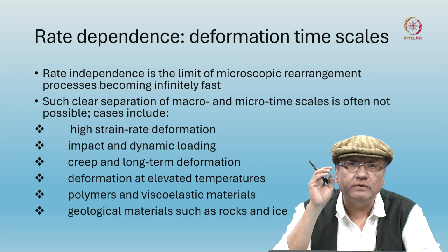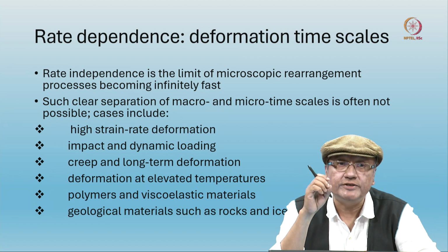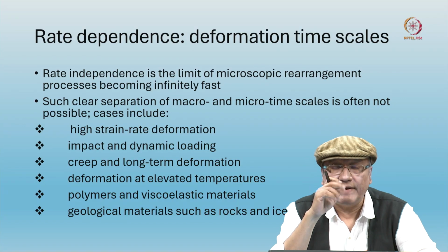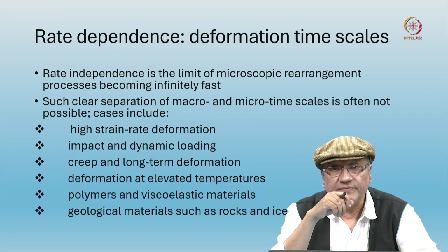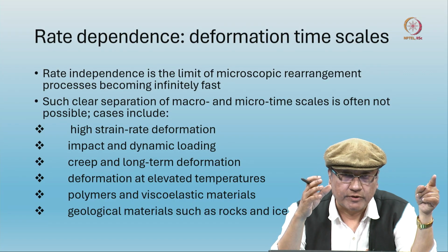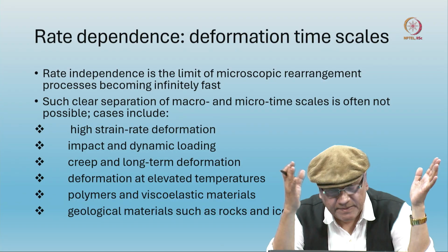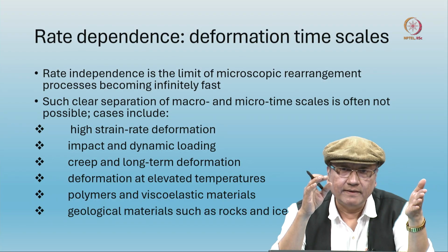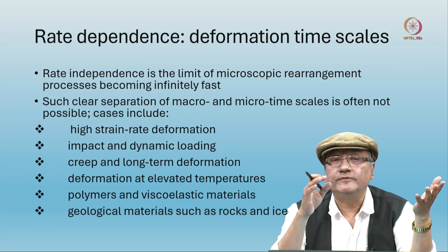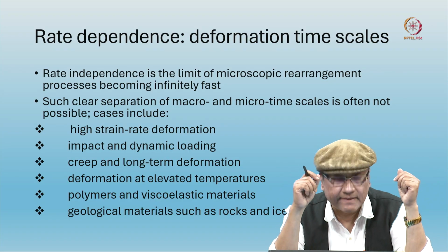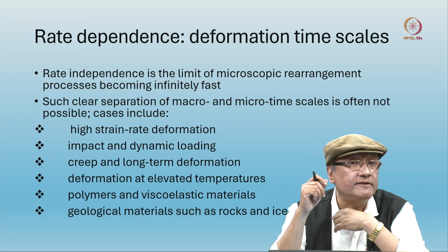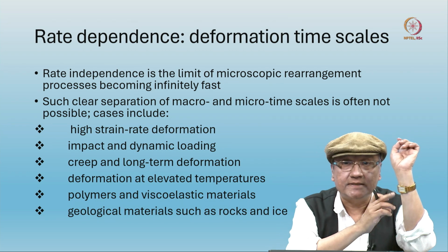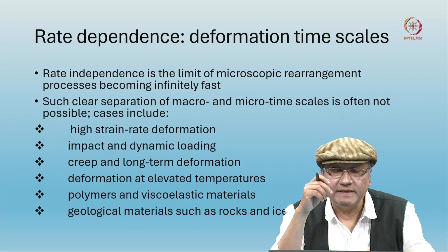Now let us talk of the time scales because of which rate dependence can come. Rate independence of course assumes that the microstructural rearrangements, all these dislocation motion, glide, climb, getting stuck while moving, it may get stuck at the interfaces of, let us say, grain boundaries and things like that, are all happening so fast that when you look at this kind of a clock, it takes no time.